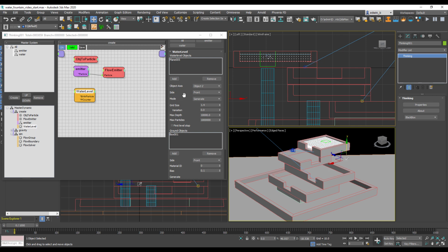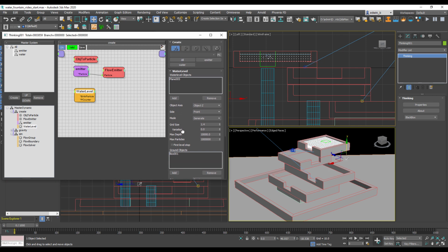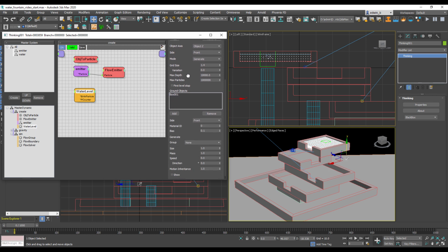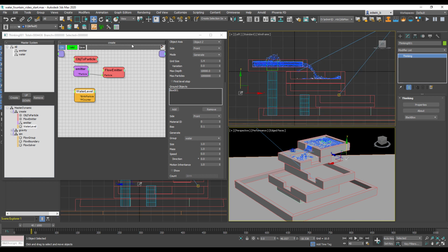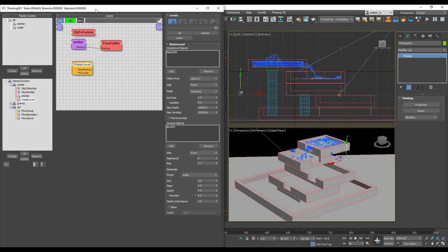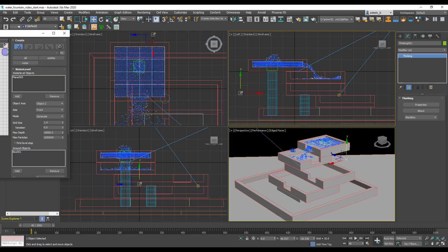Here are our particles. Now you can see they have the wrong color, they have no pressure, because we need to define where these particles are created, in which particle group. And that's done down here. So we decide all these particles go into the water group. I'll reset the simulation, and there we go. We already have a nice water pressure there, and we can see right from the start the container is filled up to the water level, and it's flowing out nicely.